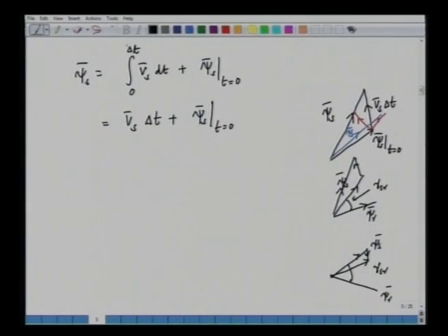So, we have the freedom to choose any one of the 8 voltage vectors, and thus we can control the stator flux accordingly. If we can control the stator flux, we can control gamma SR, we can increase or decrease gamma SR, and if we increase or decrease gamma SR, we basically increase or decrease the torque.